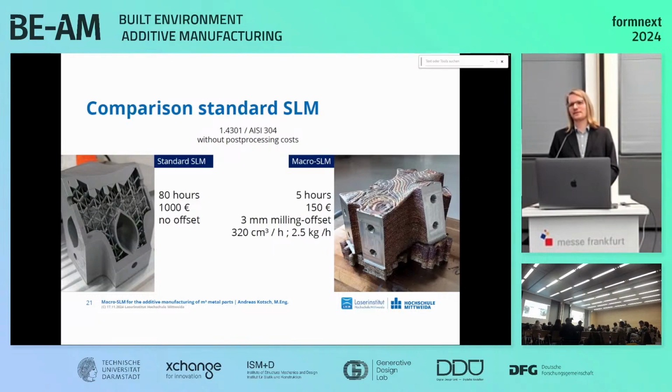But one last question. The powder bed you're applying, is it reusable afterwards, or is it getting too hot so it loses its properties? We can recycle it. Sometimes there are larger particles forming. We are sieving them and removing them, and then we can recycle the powder bed to fill the machine again. Yeah, because every time if you completely fill it up, it's 20 tons of powder, so you don't throw away 20 tons of steel powder every time.